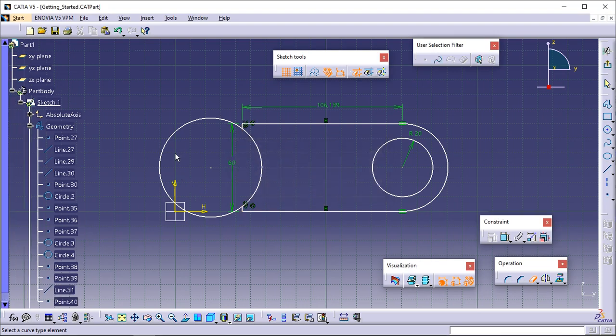Select the circle from the part outside the rectangle. The selected line and a circle part are deleted from the geometry. Note that the place where you select the geometry to be deleted is important, as it is the exact part that will be deleted. You can also use a contextual menu to delete elements.